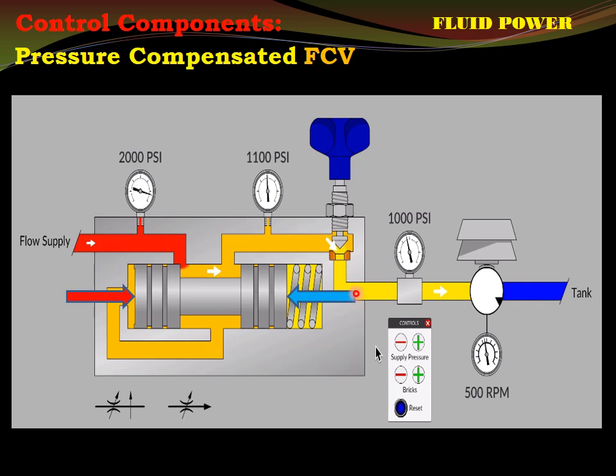That is the main spool, that is the downstream side. So this hydraulic force is because of the pressure downstream to the main spool, and the other pressure is because of the pressure upstream to the main spool. Here is upstream to the main spool, right? Apart from this hydraulic force, in the same direction the spring force is acting. Understood?